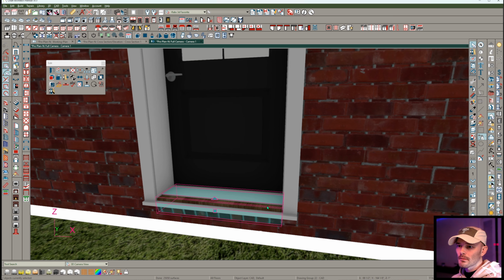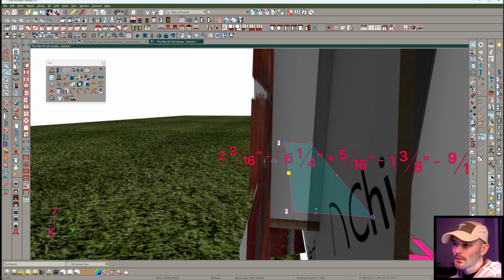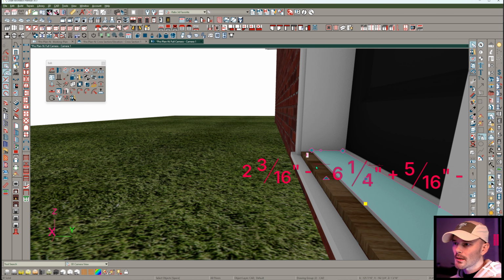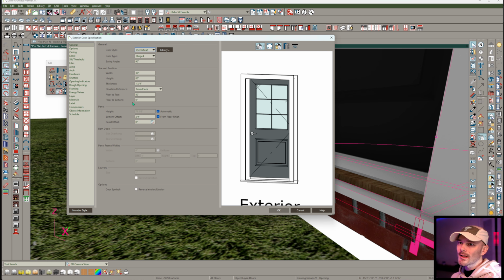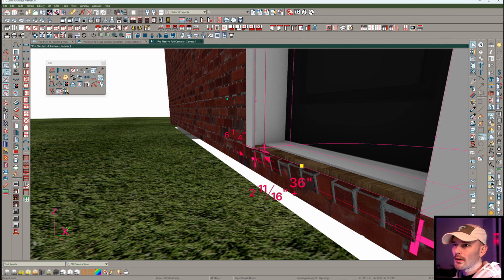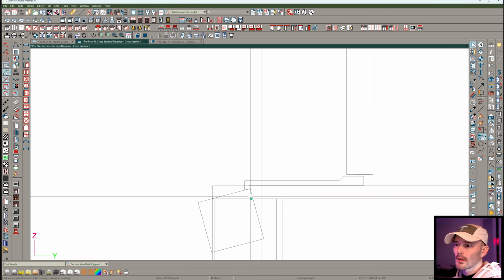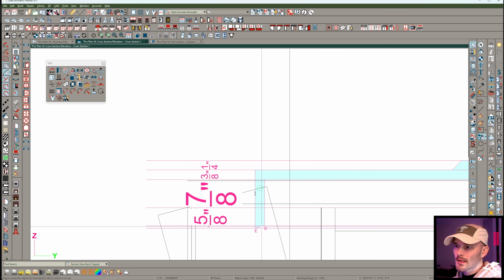Now something pops out immediately: my threshold here wasn't pushing far enough in. It's not covering the flooring, and we need it to. So first of all, let me get rid of the existing sill, so that's not fighting us. Use interior sill, use exterior sill, bam. I'll get rid of that, and then now we can come back to this cross-section elevation and see if we can't get an idea of the solid in here. Yeah. We need to move this forward so it covers the floor. That's the biggest problem.